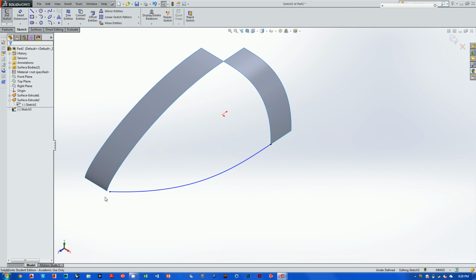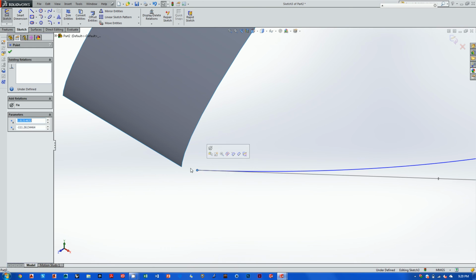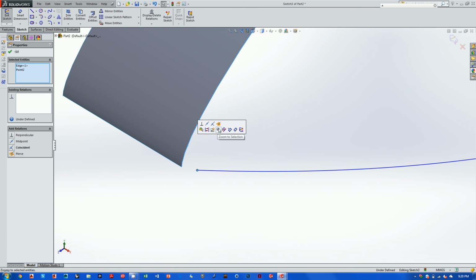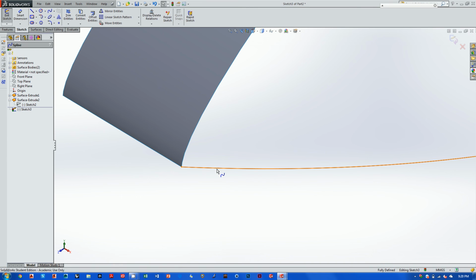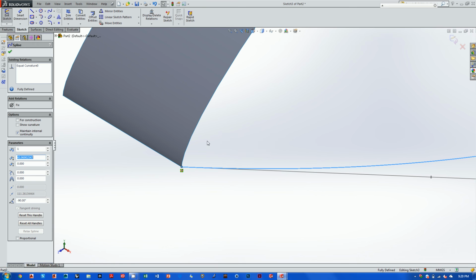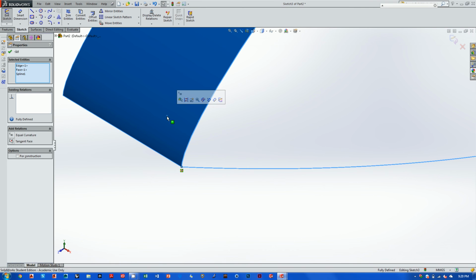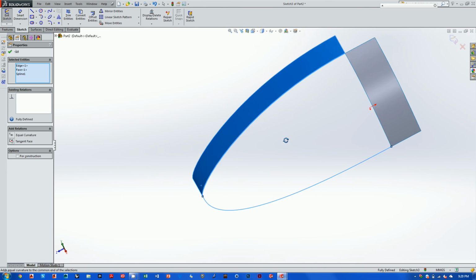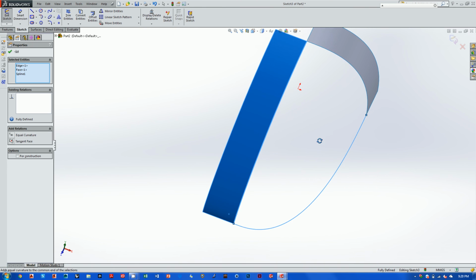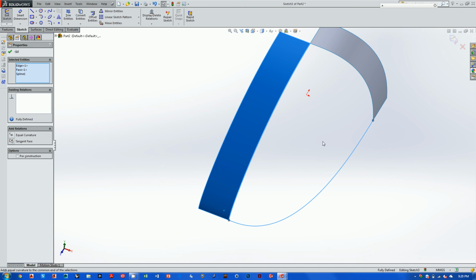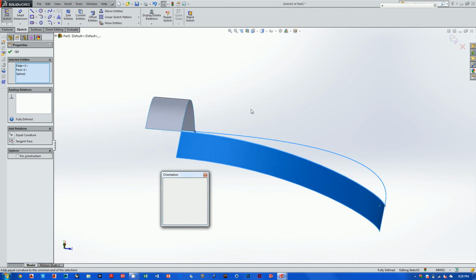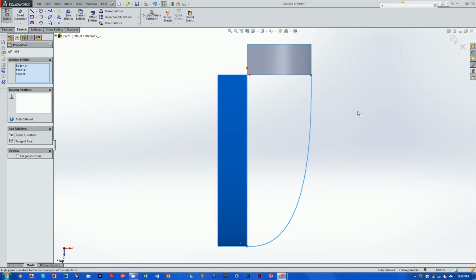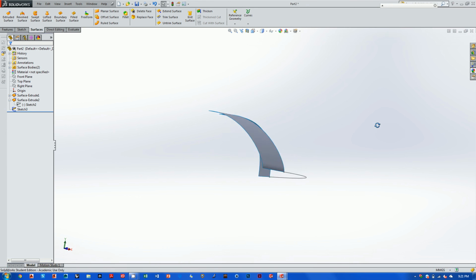Let's do this end now. First, pierce it. Pierce. Now, take the body of the curve, hold down Control, edge, surface, let go, curvature, boom. Practice this a lot and you'll get it down. Okay, there we go. Now if I look normal to it, you can see what this has done. This curve is perfectly in line with these two surfaces. We are ready to go. Okay, fantastic.